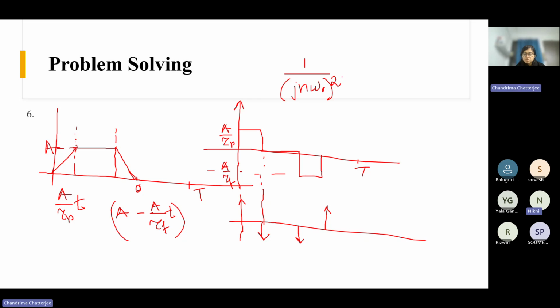We know that we want to pass CISPR 22. We want to pass electrical fast transient, electrostatic discharge, and surge immunity, all those things, to commercialize the product. Obviously we go to external certified labs to test our final product. That testing is anyway something we have to do. But if we fail the final product, then we have to redesign the entire topology, the entire circuit, the entire PCB. All this is not a one week task. It takes 2 to 3 months.